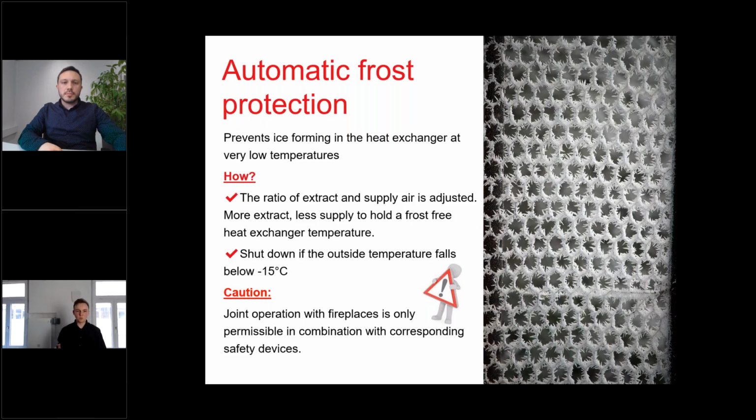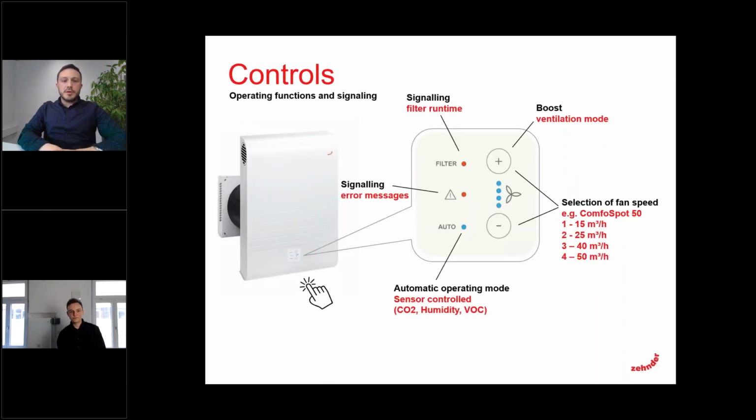And then we get a small under pressure. It's not much, but it could be enough to extract combustion gases from the fireplace into the apartment. And this can get very dangerous. So here you need to take care. Yeah, so be cautious with the fireplace if you have one.